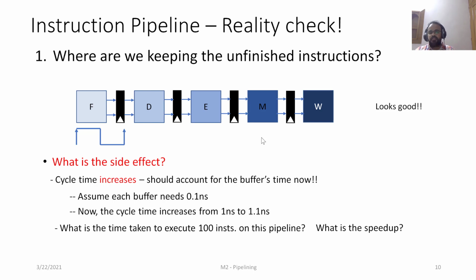Okay. Now this is an important factor that determines on how deep we can pipeline. So what we are currently looking at is only 5-stage pipeline. Now can I make it 7-stage or 8-stage or 10-stage pipeline? The more the number of stages, obviously the buffers will come into the picture and will not get enough speed up.